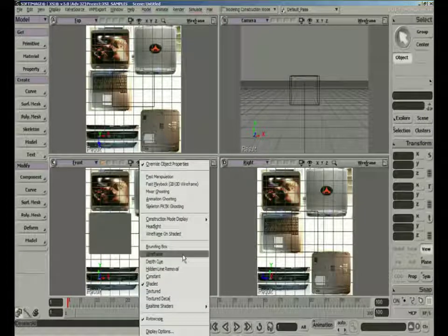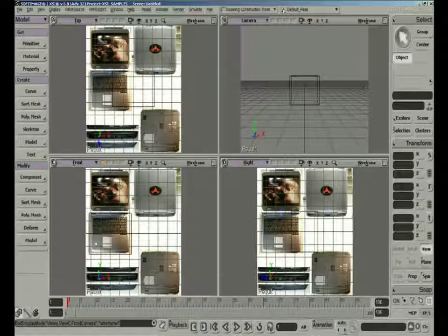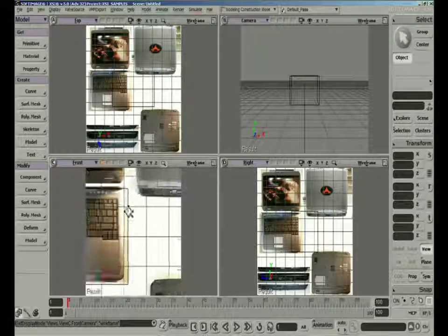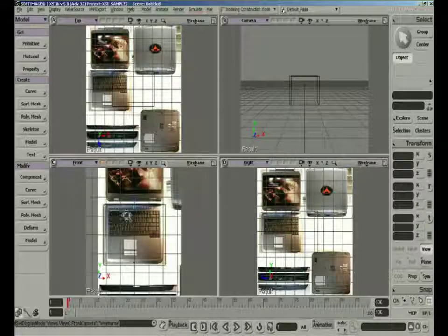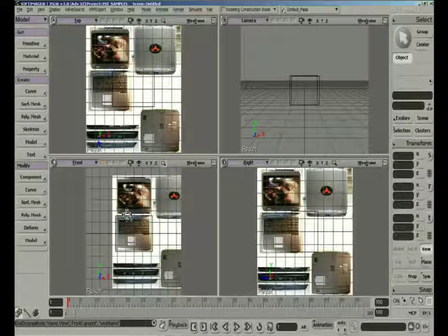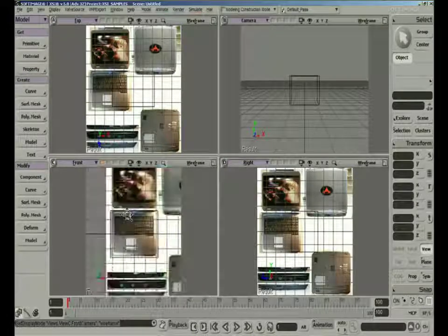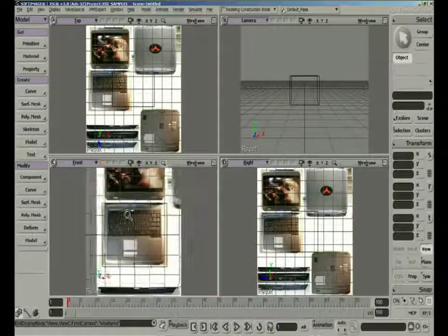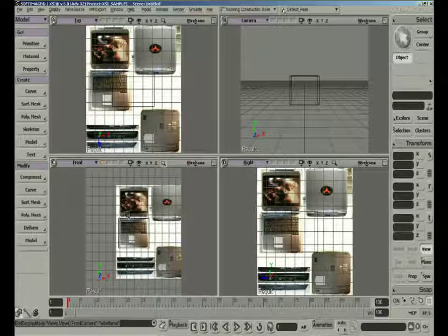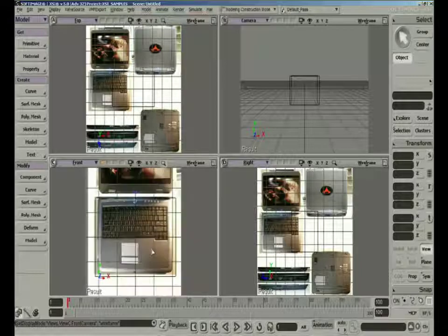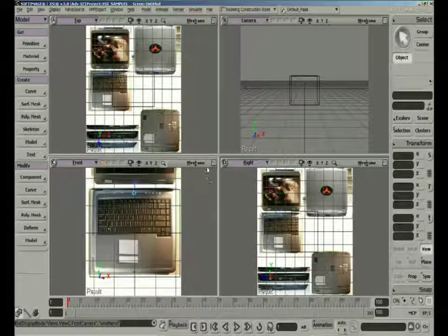Also, this is important. Once you get your grid aligned how you like it, it's a really good idea to click this little magnifying glass icon, which will lock the grid to the rotoscope image within the view. Now if you use Z to zoom or pan, the rotoscope image will move with the grid. And you can press Shift-Z to draw a rectangle zoom. If you release the lock, it can be difficult to center again. Maximize the view.